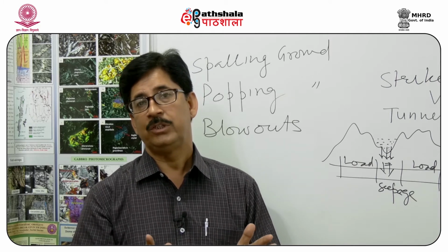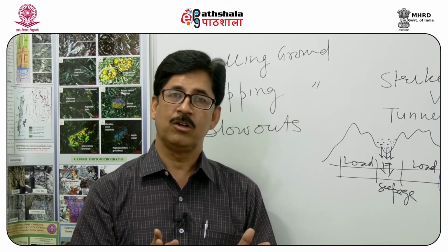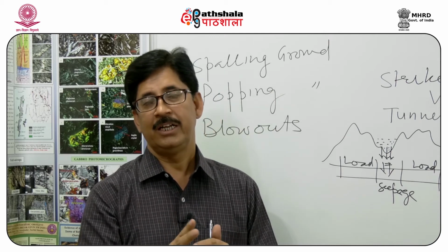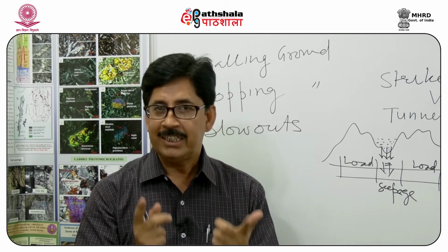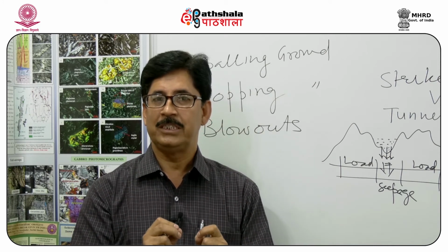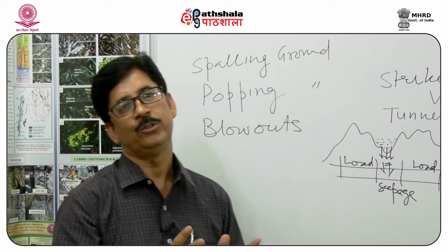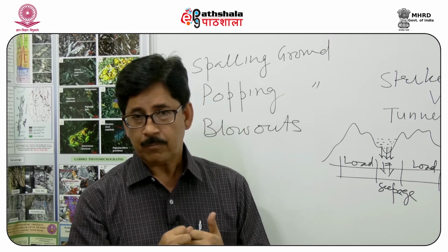Sometimes you may have a situation wherein tunnel width is less than the thickness of the rock. Rocks are striking parallel to the tunnel alignment, then all through the tunnel you will have the same rock. So tunneling in the same rock is a much better option, much better condition as compared to tunneling in different rocks.